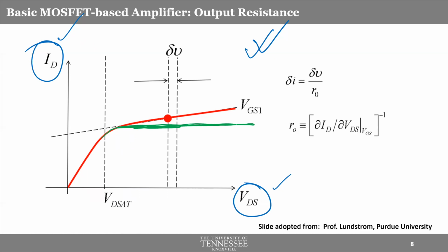To represent that the transistor has saturated. There will be no more change in current, even though you are changing VDS. Again, that's an impractical, super idealized scenario. Practically, we can never have these flat characteristics. There will always be some slope. There will be some degree of change in the drain current with changes in VDS.